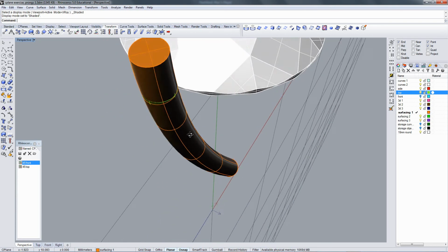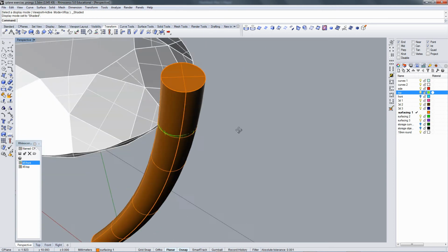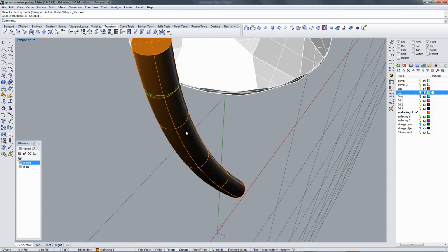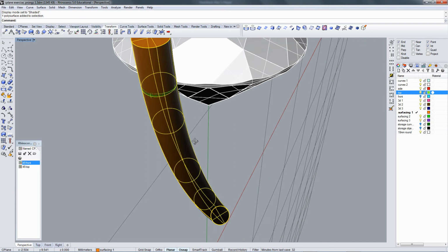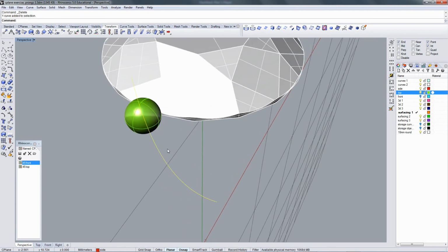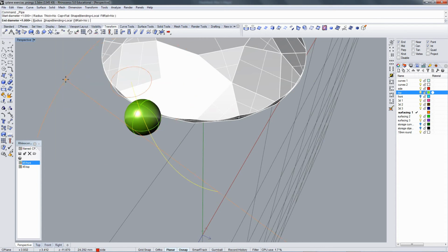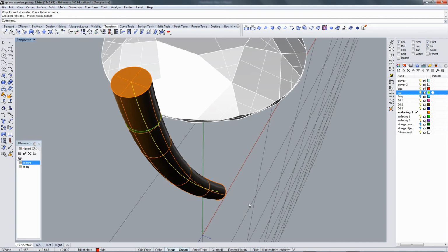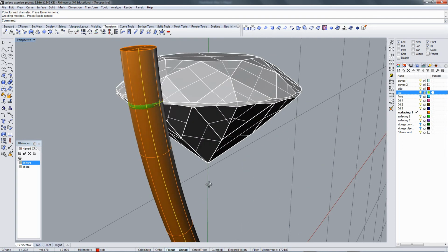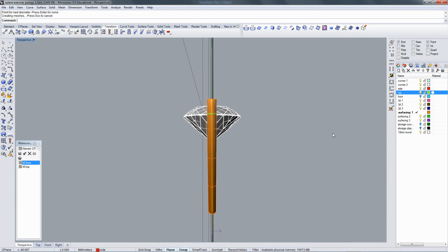So this is a nice maquette for a basic prong that's going to be straight. I want to taper my prong, however, so I'm going to actually use slightly different numbers. I'll keep it 1 millimeter at the top, but at the bottom I think I'll try 0.9. And I'll take a look at that and see what I think of that taper.